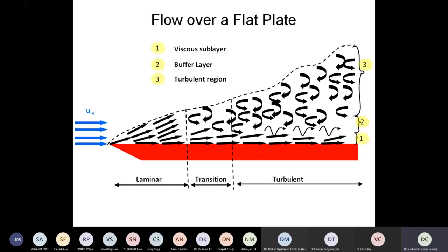So that laminar flow is not very good from the point of view of heat transfer. That is why my application demands that this laminar flow should be disturbed. Once we are trying to disturb this laminar flow, it means we have to put something over there to disturb it. So that is the concept of providing artificial elements of smaller sizes very close to the surface, so that we can trip this laminar sublayer and ultimately enhance the heat transfer rate. This is the philosophy, or the objective, for which we are trying to establish this.